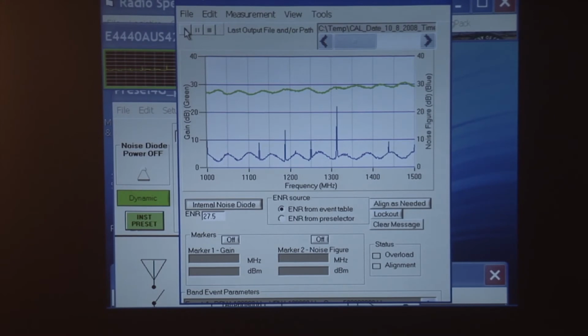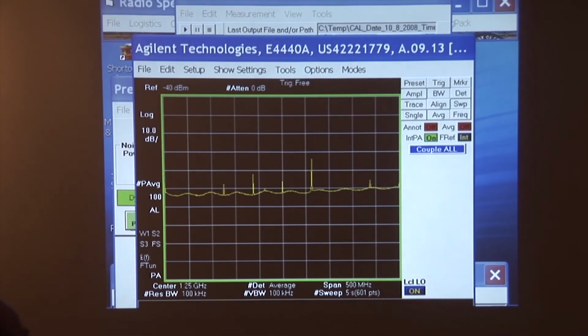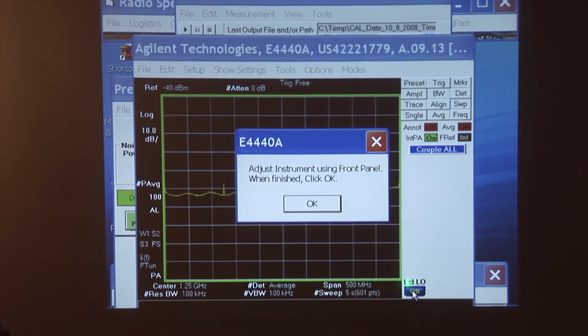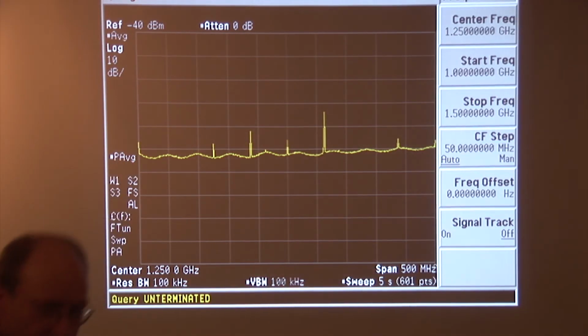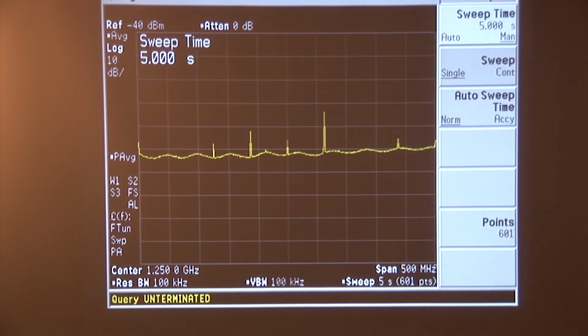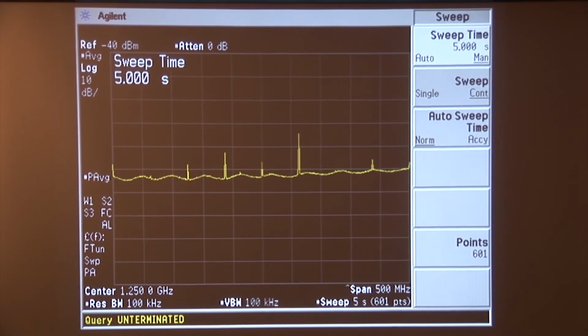We'll switch back to the spectrum analyzer display and I'll show you something. And before I do, Randy, if you would go to manual mode on the spectrum analyzer. The software locks out operator control when it's running. And now that we're in manual mode, I'm going to switch the projector back, excuse me a moment, to the spectrum analyzer, show you what's going on here with this amplifier turned on versus turned off. Get this thing sweeping. Right now we're looking at the spectrum analyzer display with the amplifier turned on. We have these ambient signals that are actually leaking into the measurement system.